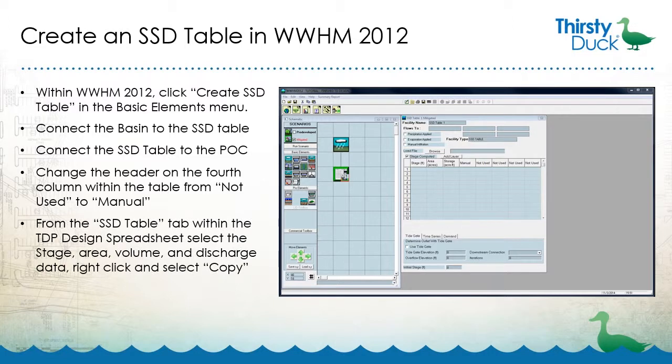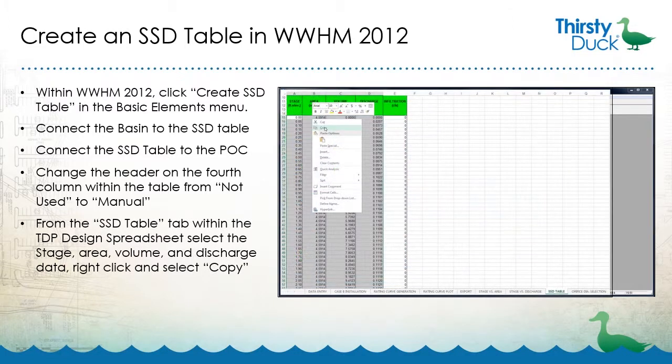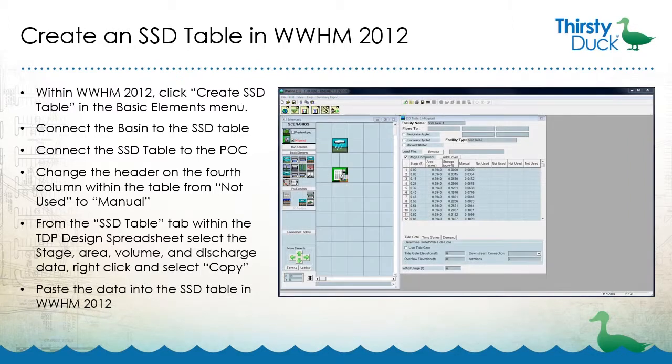From the SSD Table tab in the TDP Design spreadsheet, select the stage, area, volume and discharge data. Right-click and select Copy. Paste the data into the SSD table in WWHM2012 and finally run the scenario.